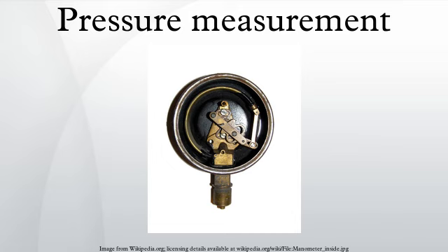There is another way of creating a sealed gauge reference, and this is to seal a high vacuum on the reverse side of the sensing diaphragm. Then the output signal is offset so the pressure sensor reads close to zero when measuring atmospheric pressure. A sealed gauge reference pressure transducer will never read exactly zero because atmospheric pressure is always changing and the reference in this case is fixed at 1 bar.